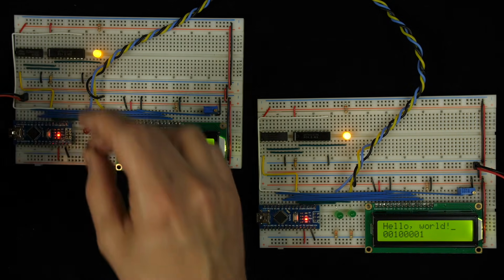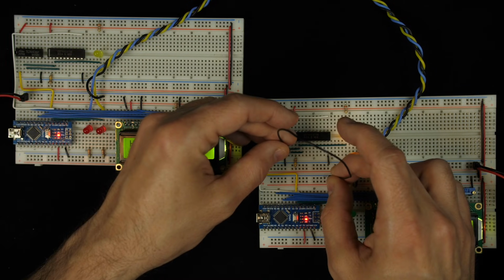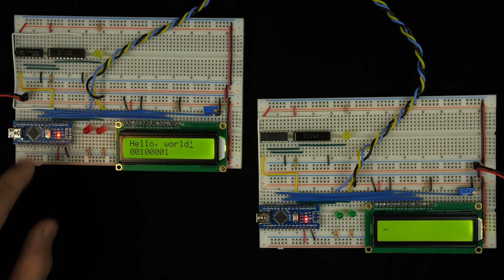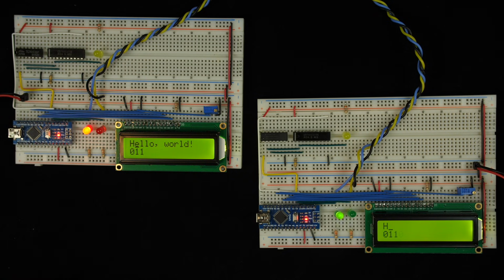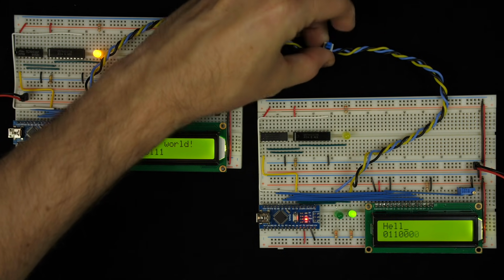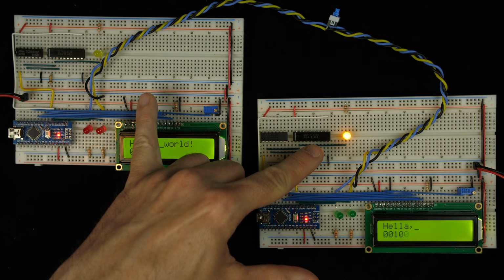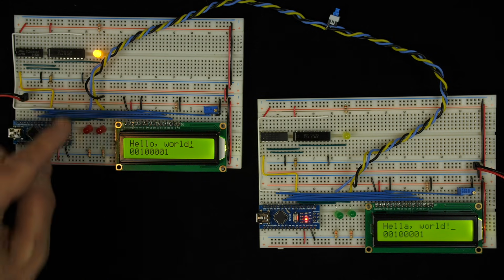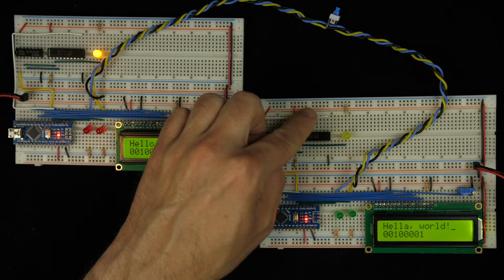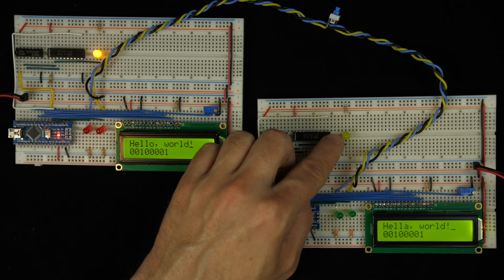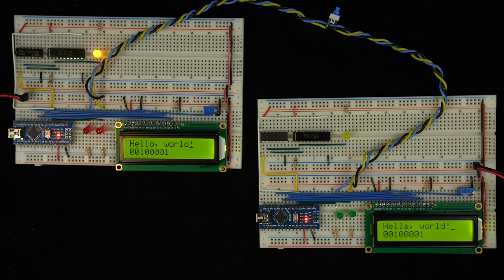So now let's reset everything and try introducing an error. So first I'll reset the parity bits by briefly connecting pin 1 to ground. Then I'll reset the receiver, and now reset the transmitter to resend the message. So now let me try to introduce an error. And already you can see the parity bit is out of sync. And so if we just speed this up so it finishes up. And so now at the end of the message, we can see the transmitter thinks it sent an odd number of 1s because the parity bit is on, but the receiver thinks it received an even number of 1s because the parity bit is off. So that means there was definitely an error, and this message here, hello world, is apparently not what we sent.